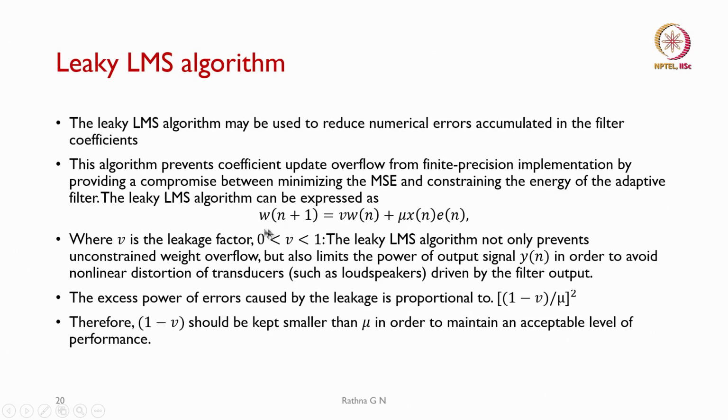It is given by the expression v times w of n plus mu times x of n times e of n, where v is the leakage factor, which is going to be between 0 and 1. If it is 1, we know that it is the LMS algorithm.